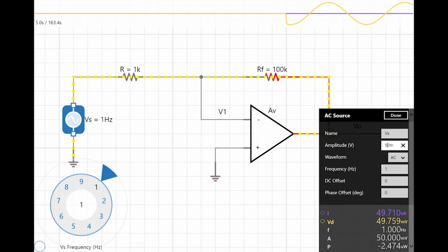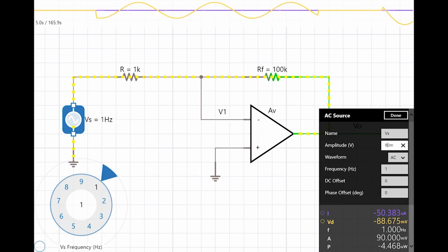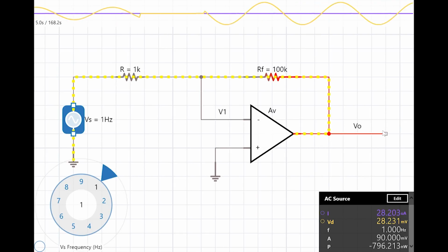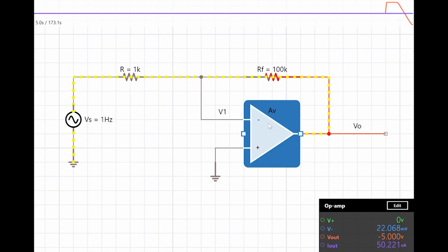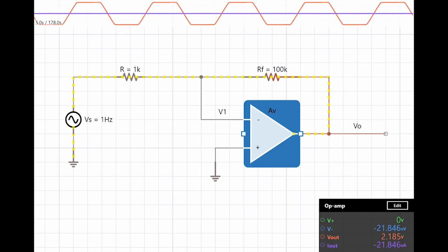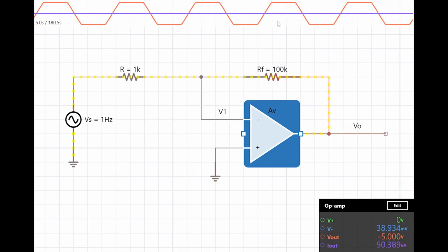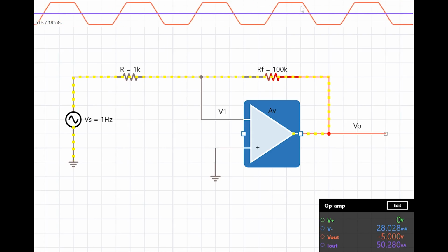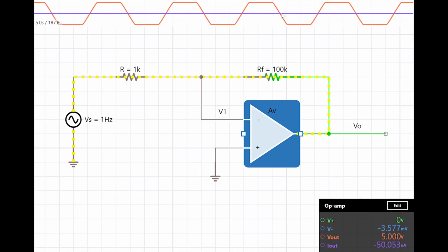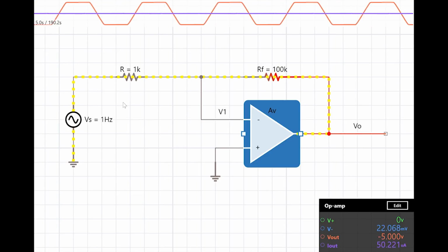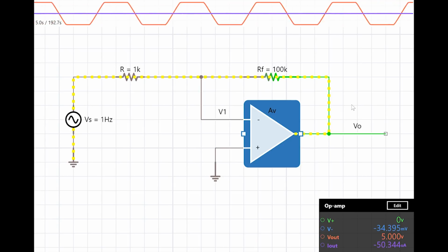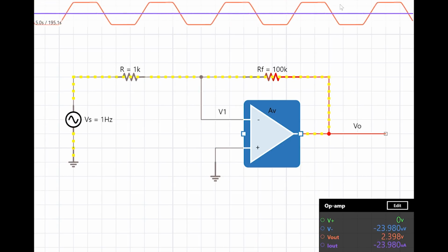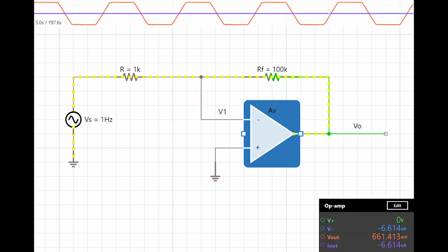Now let's say my input is a bit stronger and it is of an amplitude of 90 millivolts. In this case, my input is again a proper sine wave, but when I look at my output, till the amplification takes the output to a value of 5 volts, it's coming up properly, but then the output cannot go above 5 volts, and if the amplifier is trying to push the voltages to 6 volts, it cannot go. So the top and the bottom of the sine wave is now clipped off.